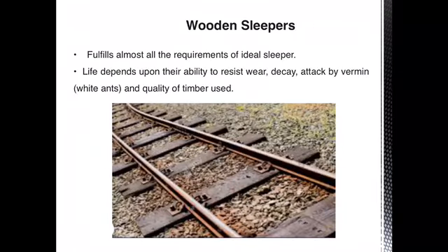The first and foremost one we have is the wooden sleeper. The picture here shows the wooden sleepers used in the construction of the railway track. Wooden sleepers are regarded as the best among all, and they fulfill almost all the requirements of an ideal sleeper. But the drawback of wooden sleepers is that they have very little ability to resist wear and tear, and they are subjected to decay and attacked by vermin. Vermin is nothing but the white ants. The entire life of the wooden sleepers depends upon the quality and the seasoning of the timber we have used.